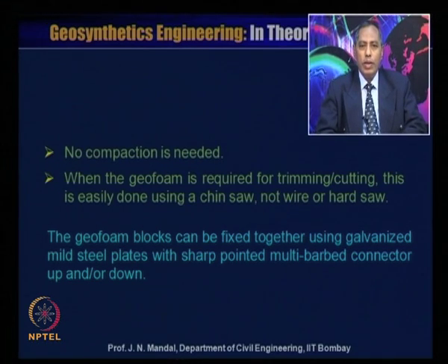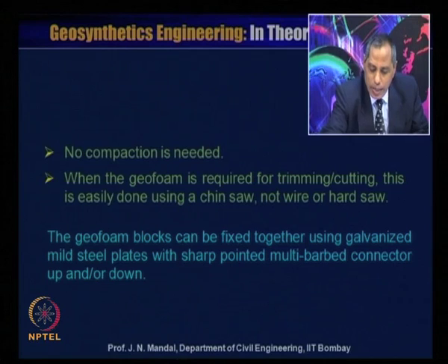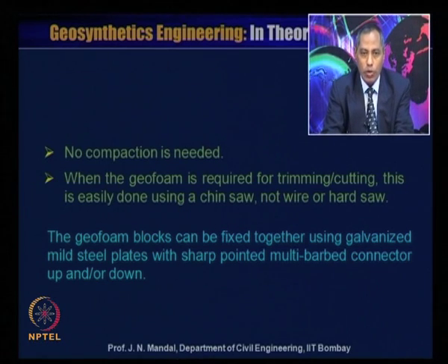When the geofoam is required for trimming and cutting, this is easily done using a chain saw, nut saw or hand saw. The geofoam blocks can be fixed together using a galvanized mild steel plate with sharp pointed multi-barbed connector up and down. So I am giving one small